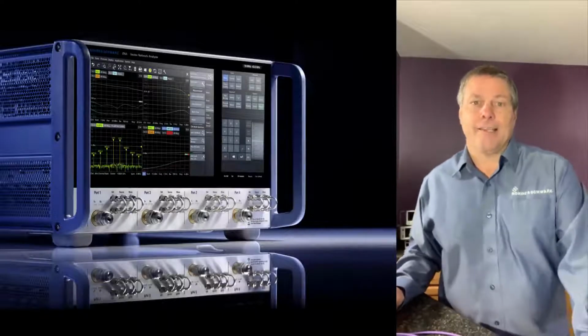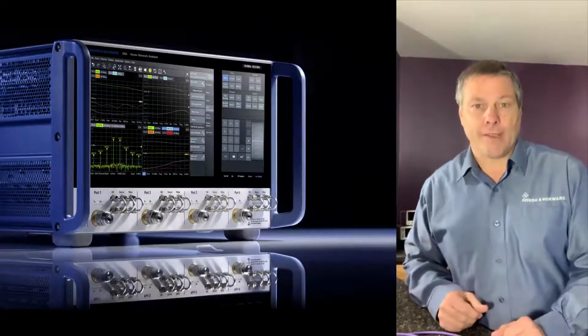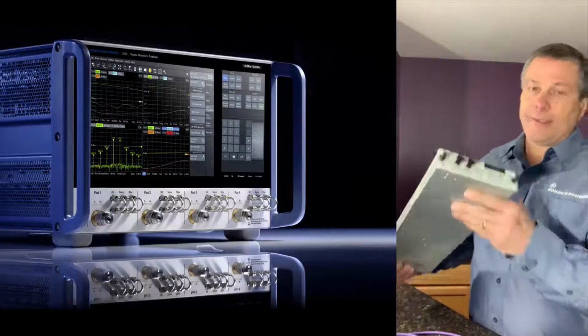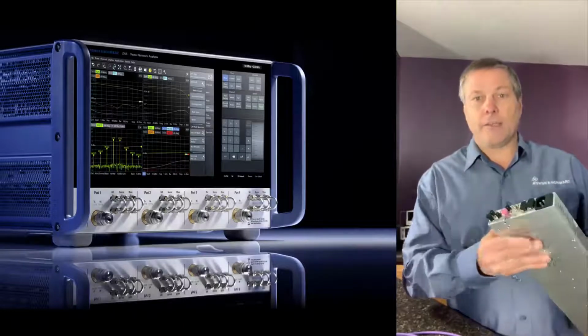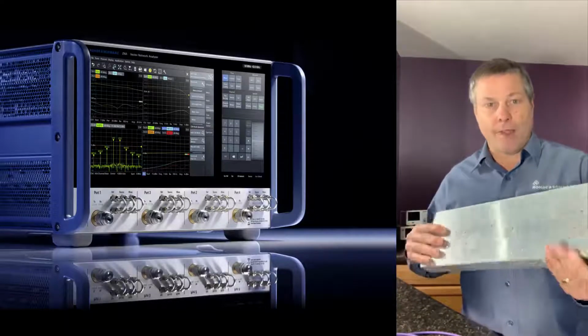I have 10 techniques that I'm going to share with you for improving your group delay measurements on frequency converting devices that have embedded local oscillators. So I mean devices such as this MyTech satellite block down converter, which takes a 20 gigahertz input signal and down converts it to about 1 gigahertz using an embedded local oscillator operating at 18.75 gigahertz.